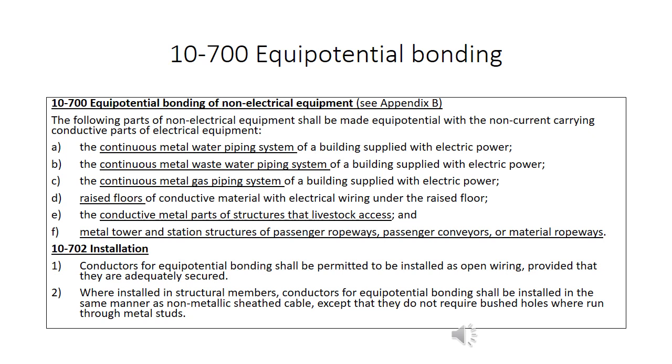The problem that may result if you do bond on the flexible piping is you are going to damage the piping and thereby allow gas to escape. So you only bond on the rigid steel portion.